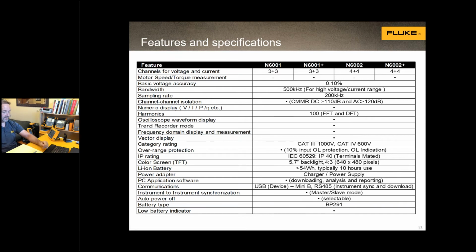The advantage of doing some of these motor efficiency measurements is that one is NEMA ratings. If you deal with motors in a facility and you want to characterize the motor, you could use NEMA as a comparison to understand how hard you're pushing the motor. NEMA provides guidelines on running your motors and also provides guidelines for derating the horsepower of your motor to improve its operational life.